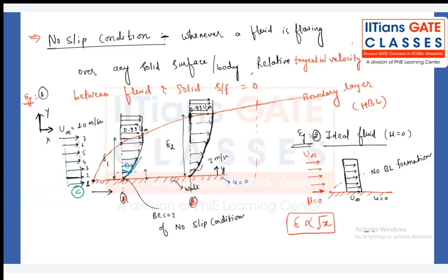See, the moment solid particles are there, suppose there is a solid surface. The first fluid layer which is coming in contact with the what? Fixed plate. Now between this first layer and this fixed plate, there has to be certainly some communication happening. And because of the viscosity, there will be certainly some resistive forces developed on the first fluid layer.